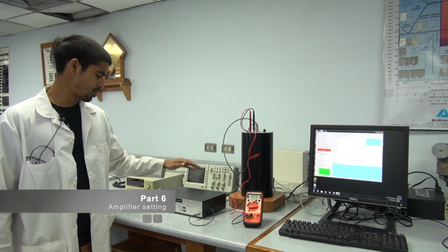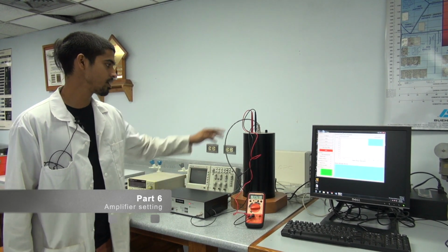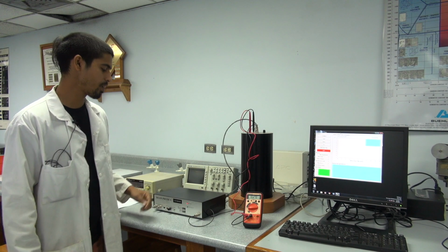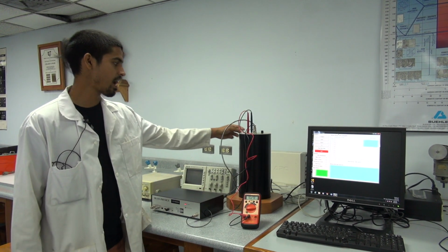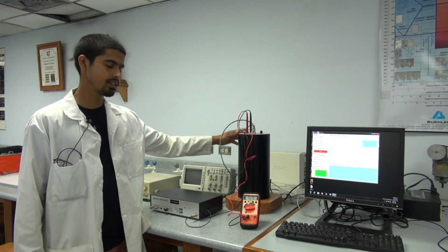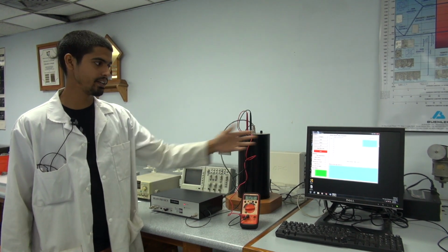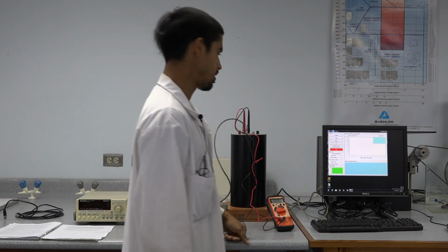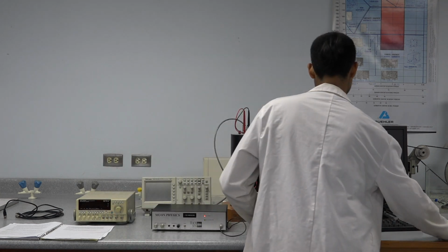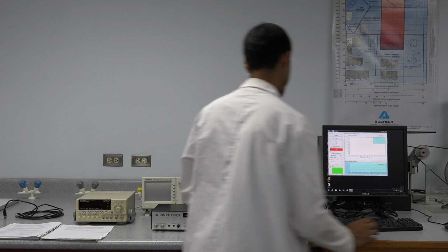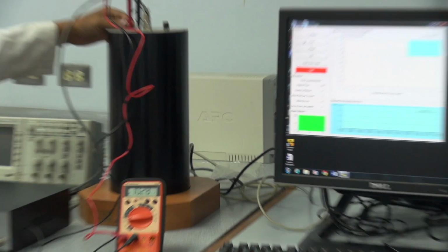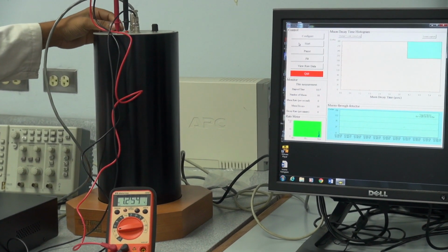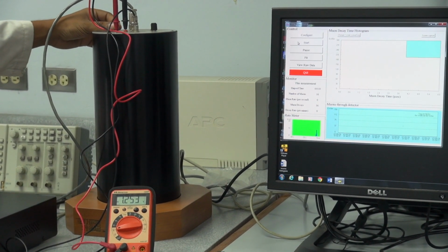So now I've moved the voltmeter from the electronics box to the scintillator tube. And now we're going to do the same thing that we did with the discriminator setting. We're going to adjust the high voltage adjust on the scintillator tube, and we're going to find the ideal value on the software. So let's start. I'm turning the voltage down to a very low voltage.